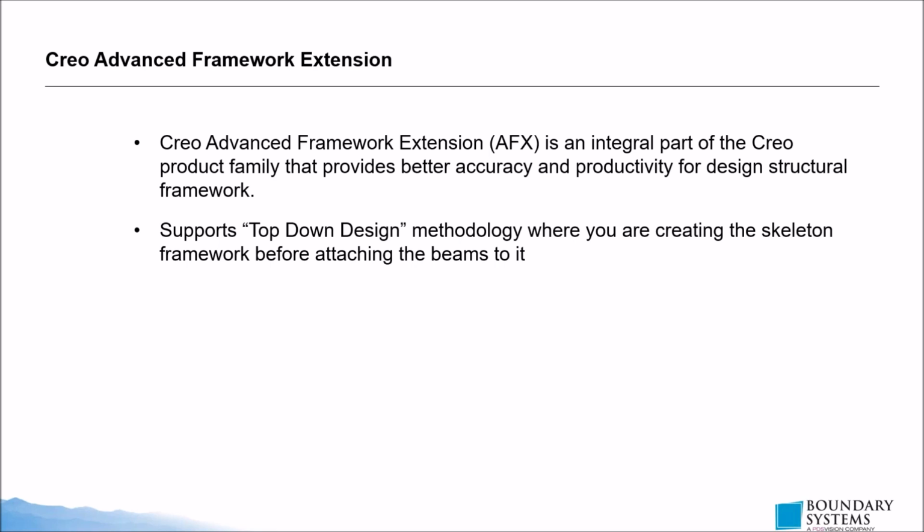It supports the top-down design methodology, where you're creating a skeleton framework before attaching the beams to it. If you're not familiar with top-down design methodology, you're basically creating a framework of curves. If you're using skeletons, you'll also use surfaces, things like that. You can do that same basic thing here in Framework Extension by simply creating the skeleton of what you want your structure to look like.